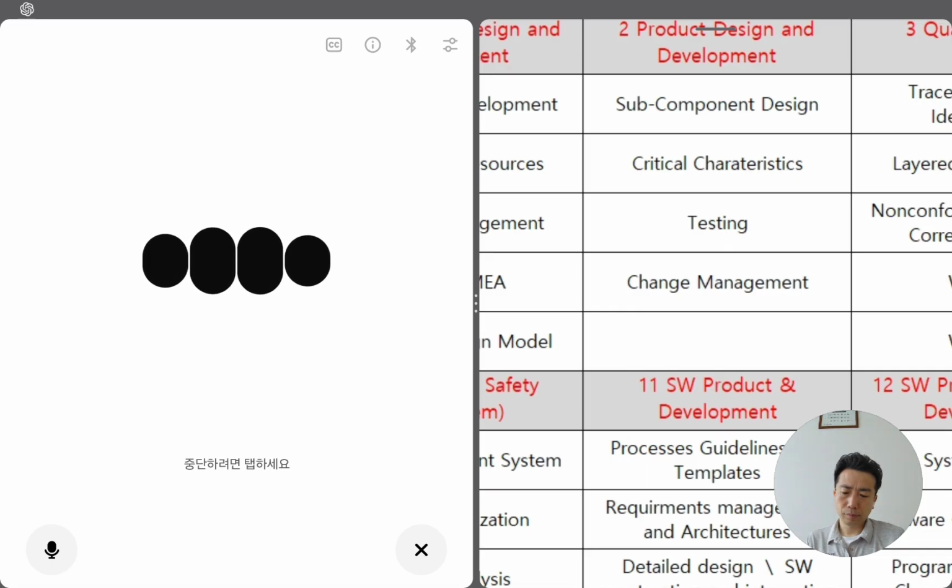2. In DFMEA, Design FMEA, characteristics linked to high severity ratings, S 9 or 10, are marked as critical. These are flagged in the DFMEA table, often with CC/SC notation or color coding. 3. In PFMEA, Process FMEA, special process controls are identified when a critical characteristic is affected, marked with a CC/SC symbol in the PFMEA sheet. Control methods like poka-yoke and 100% inspection are listed in the controls column. 4. In control plans, critical characteristics are clearly marked in the control plan table. Columns often include a CC/SC flag, triangle, diamond, or text. The plan describes the special control method, e.g., 100% inspection, SPC, special gauge.